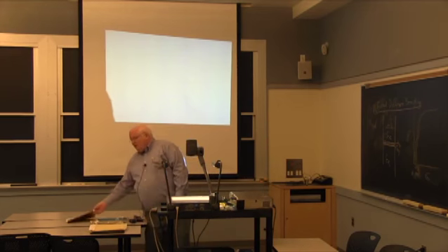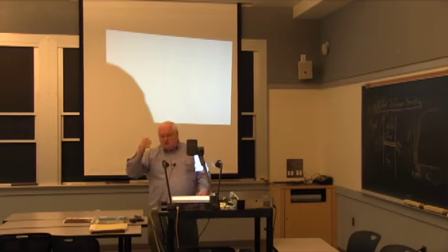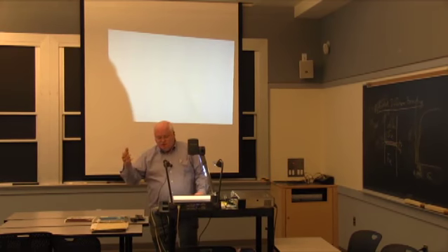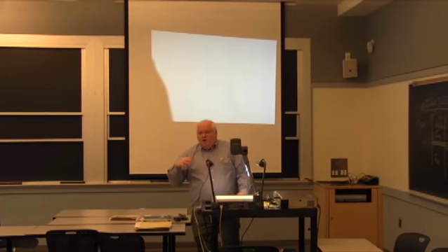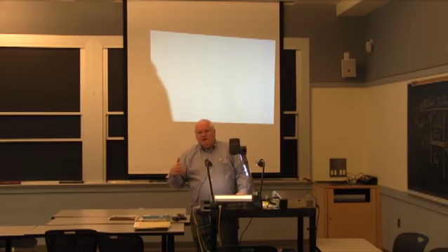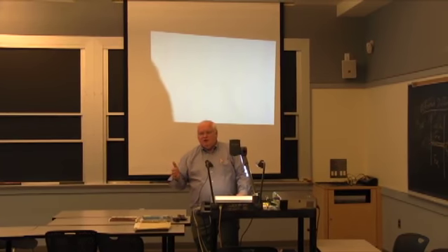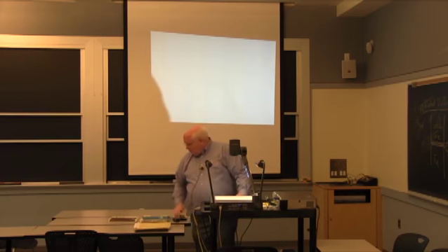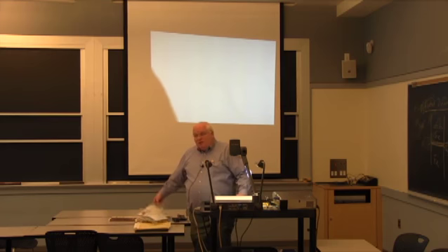So, it turns out soldering and brazing are the exact same process. One occurs at high temperatures, one occurs at low temperatures. How did we get to this state of two different sets of terms? Well, we got there because soldering came first. Soldering's been done for thousands of years. I showed you these little solder beads on the Etruscan earrings and King Tut's dagger, we think, where they basically were soldering with tin. And tin has a melting point below 450 C, it's 232 C, so far as that goes. So it's soldering, but they actually ended up forming a transient liquid phase diffusion solder joint.